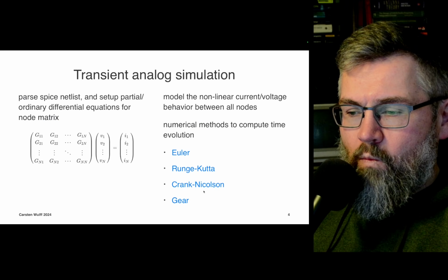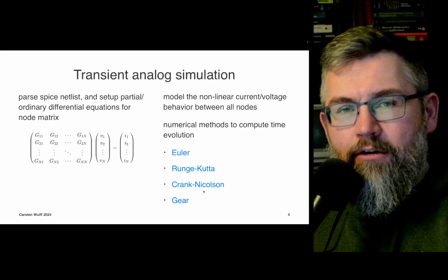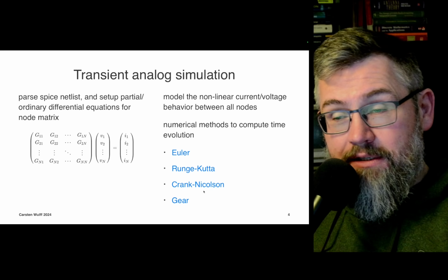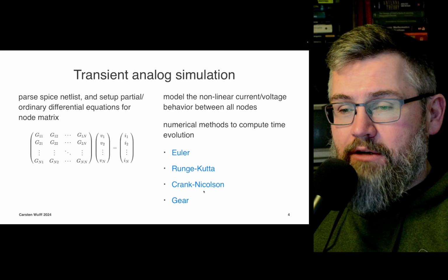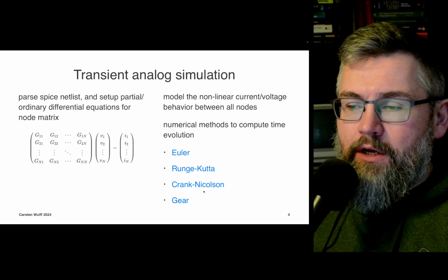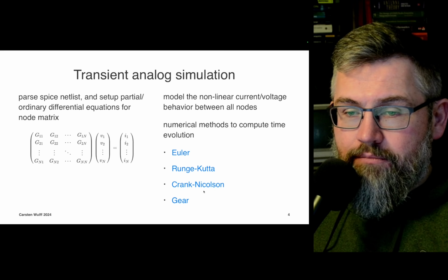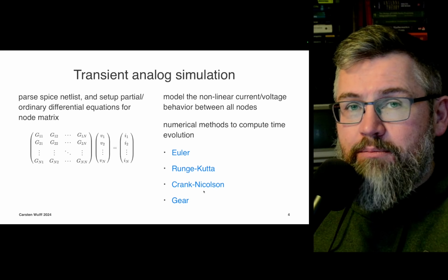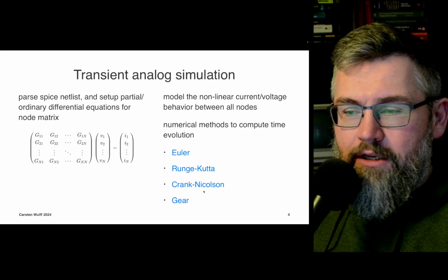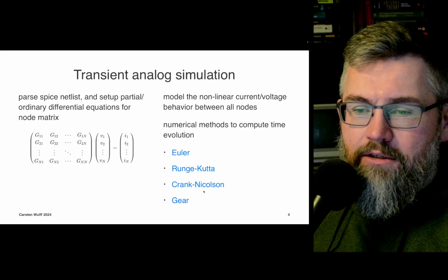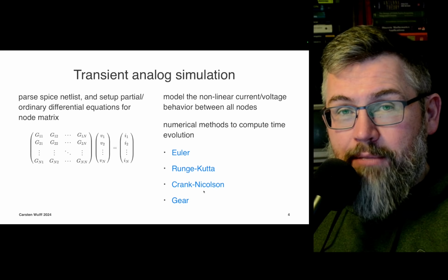But the analog circuit that we want to simulate has to be simulated in an analog simulator because it can't use a digital simulator. One of the reasons is we don't know what the time step should be, because the speed of an analog circuit depends on the components, the resistances, the capacitances, and transistors, and it can be non-linear.